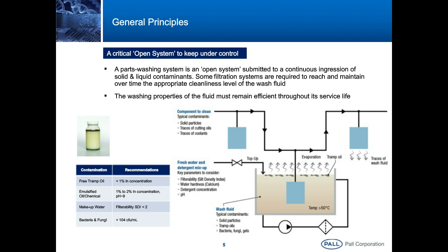The table gives you some guidance for a few key fluid parameters like the tramp oil concentration, the filtrability of fresh water, the pH, etc.